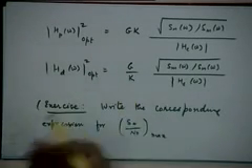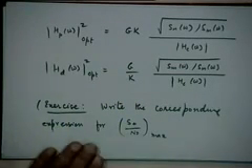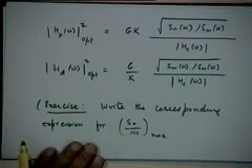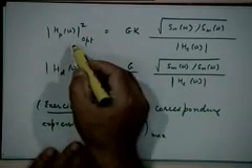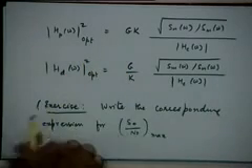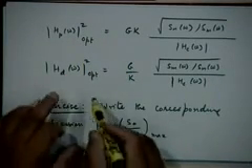So I must boost up those frequencies at the transmitter where I expect a large amount of noise energy to be present. That part of the spectrum should be emphasized. That's what the pre-emphasis filter will try to do. So the optimum pre-emphasis filter has to do this.